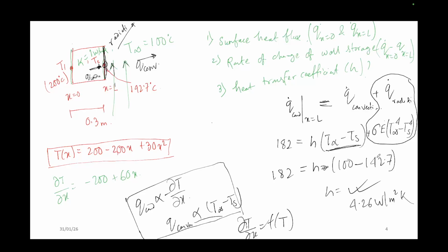If you convert 100 degree into Kelvin, you get 373, and 80 degree into Kelvin is 353. If you subtract, you get 20 Kelvin. So 20 Kelvin or 20 degree centigrade is the same if it is a temperature difference. So no need to change Kelvin into degree centigrade in h. Okay, I'm moving to the next one.